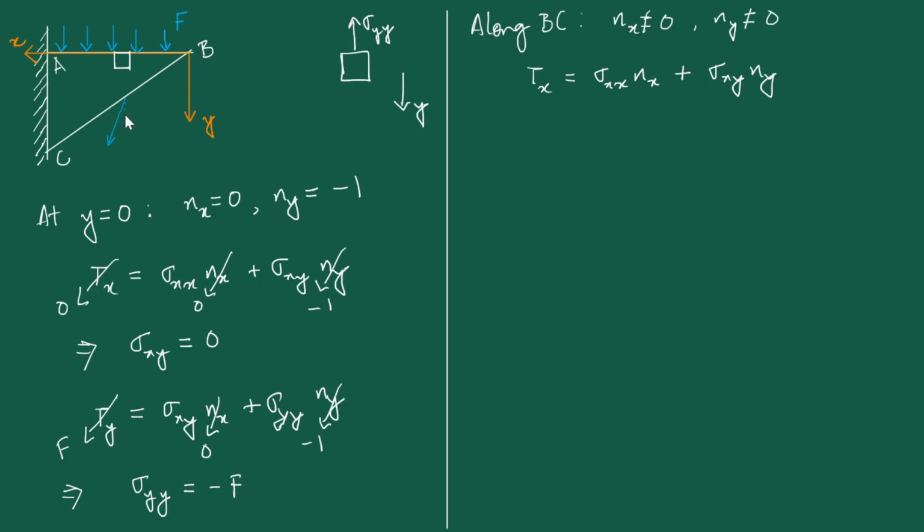It will have a y component like this and an x component like this, maybe not so long. Now it is very important to note that because this particular traction vector is 0, because we do not have any loading on this, both the ty component, represented by this dotted vertically pointing downward arrow, and the tx, this leftward pointing dotted arrow, are 0.